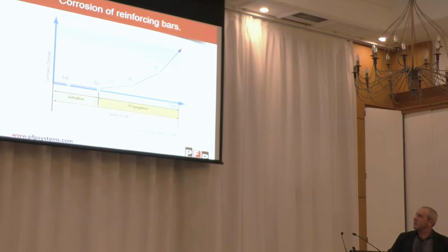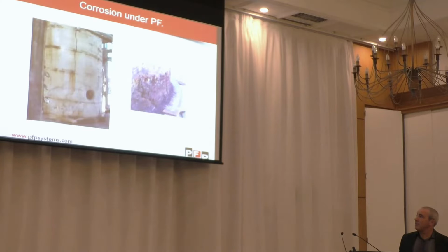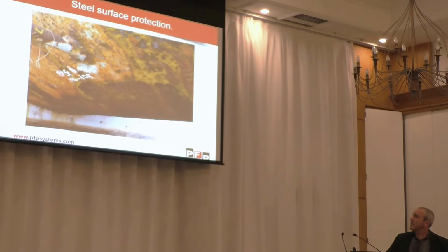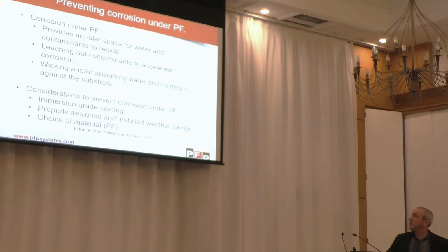Really, we need to make sure that we're not causing any corrosion of both the subsurface and the system holding the cementitious fireproofing together. Here's a couple of examples of a system that's clearly corroding, and then one that's been removed showing the underlying damage. We don't want our vessel or asset to look like that once we've been able to remove the system.